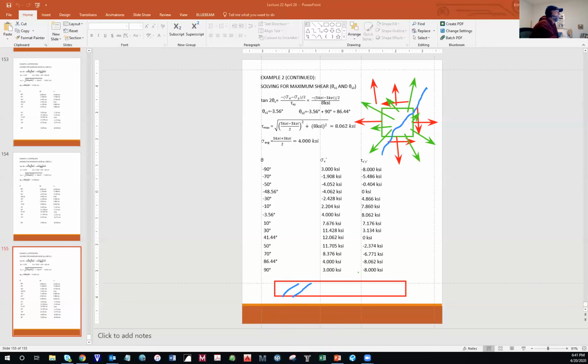Okay, well, part of my understanding of, wow, what happened? What am I looking at? Is my understanding of these principles. And these principles are telling me that concrete is weakest in tension. That is its weakest direction. So that tells me that the principal tensile stress is in this direction, and the principal compressive stress is 90 degrees or opposite in that direction.